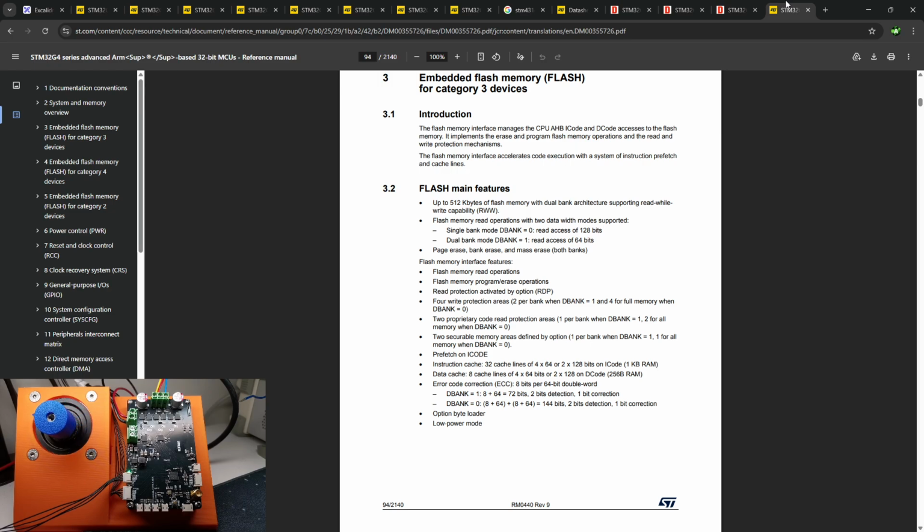So actually, now that you forced me to face reality and Google options of STM32G4 microcontrollers, I would say that I will try to upgrade actually to the one with 5 ADCs. And I don't need 5, I only need 3. But having 2 flash banks will be very useful for the future. And maybe we will do a stream, or multiple streams, with me developing bootloaders.